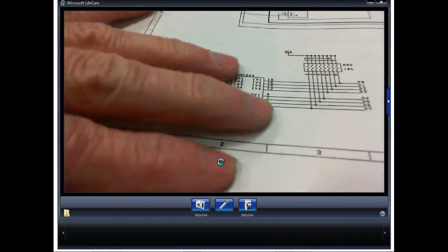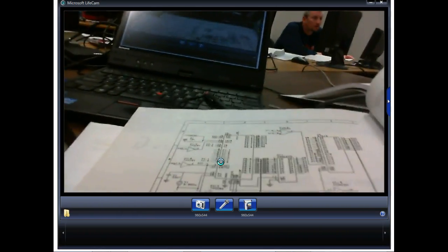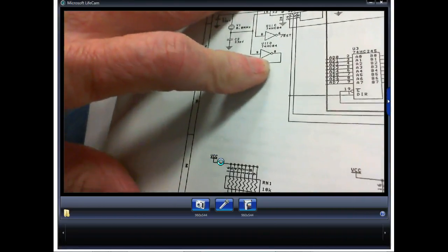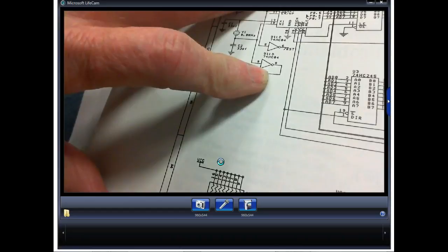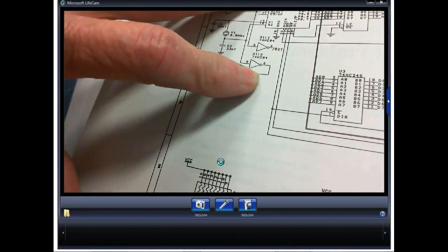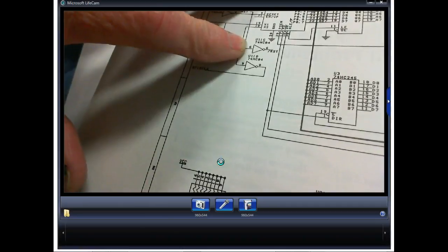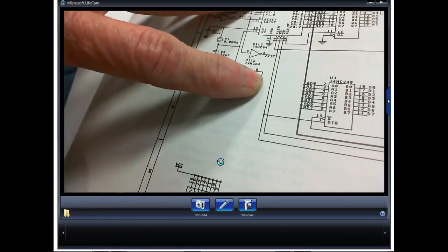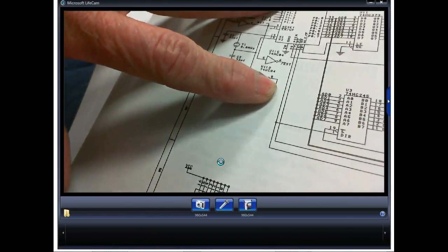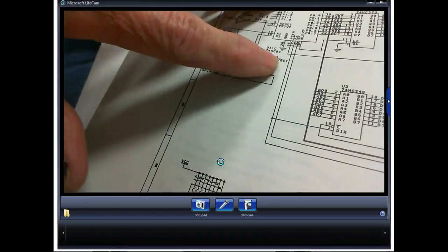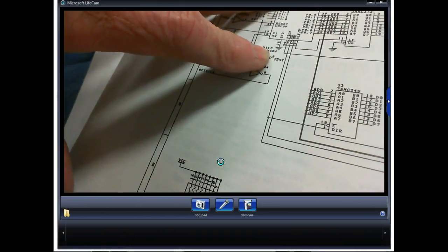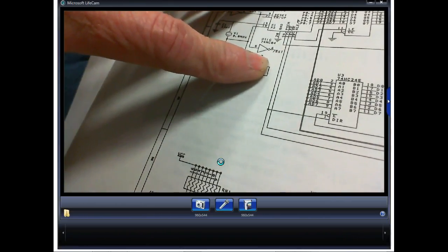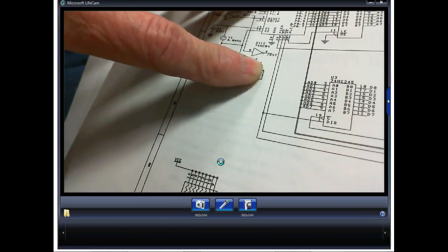Now, this is combinational logic. We're not going to get into that. But right up here, this is an inverter. So here's U1. You see where I'm at? Well, how can this be U1 and this be U1? If you look at the pins, one of them is using pins 5 and 6, and the other is using pins 9 and 8. So they're just inside the same chip. Now, some guys don't do this, but this one does, and we'll show y'all later on. Notice one of them is called U1:C, and the other one is called U1:D. So sometimes they give the individual gates letters.